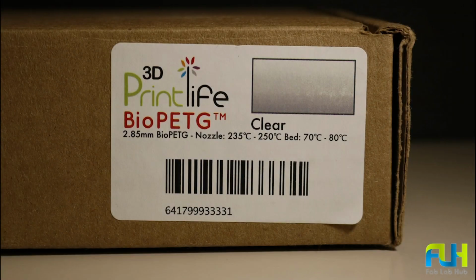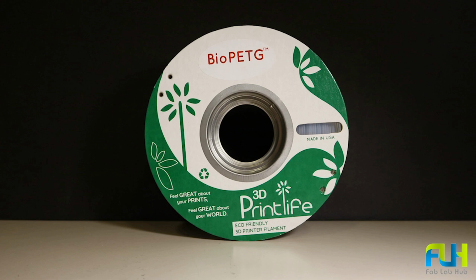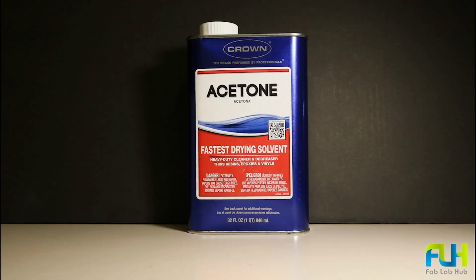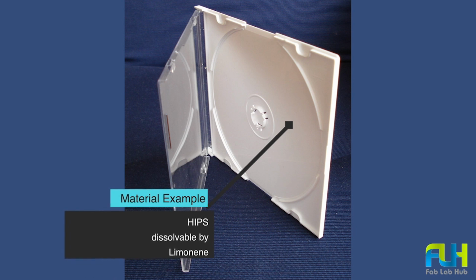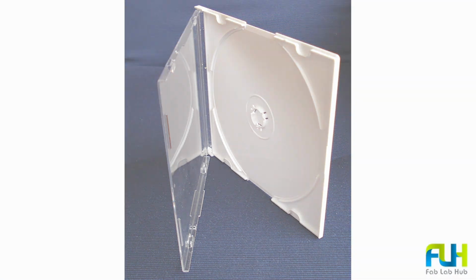If your final product will come into contact with chemicals, you will want to choose a material that is highly resistant to chemicals. The best choice for this is PETG. Certain materials are extremely sensitive to specific chemicals. For instance, ABS is highly sensitive to acetone and will dissolve if it comes into contact. This property can be exploited during post-processing, where acetone can be used to smooth ABS parts. Similarly, HIPS dissolves in limonene and can be used as a soluble support that can be easily removed with an application of the chemical.